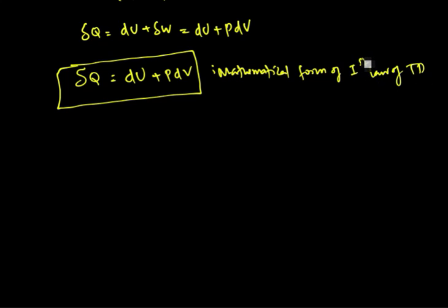So the first law states that heat supplied to a system is equal to the increase in the internal energy of the system plus the external work done by the system. What we have to remember from here is that, as I told you in the previous lecture, the internal energy has two parts, the internal kinetic energy and the internal potential energy. If you consider an ideal gas, the intermolecular interactions are not there. The internal potential energy is due to the intermolecular interaction or attraction between the individual gas molecules of the system.